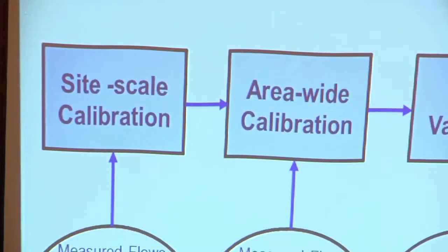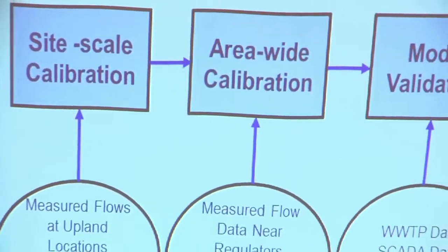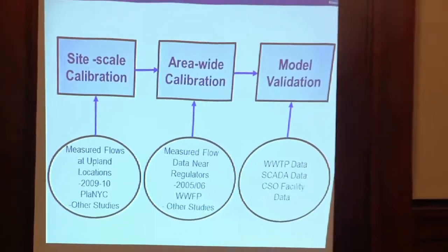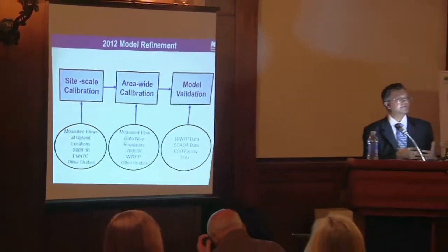And once we performed this hydrology calibration, we moved on to what we call area-wide calibration, which is looking at the interceptor system or regulator structures and so on. These are heavily influenced by the hydraulics of the system.